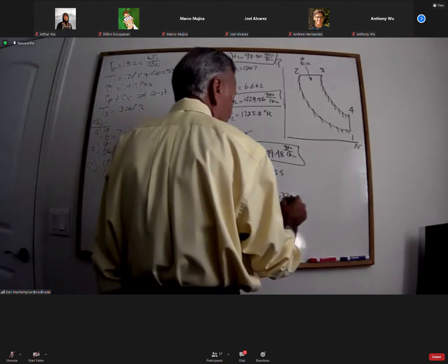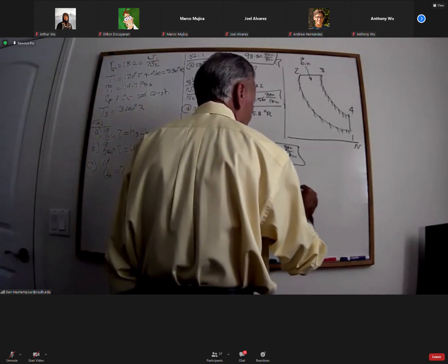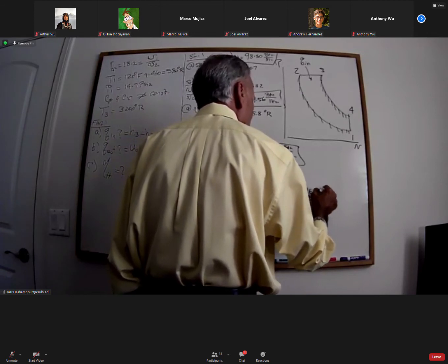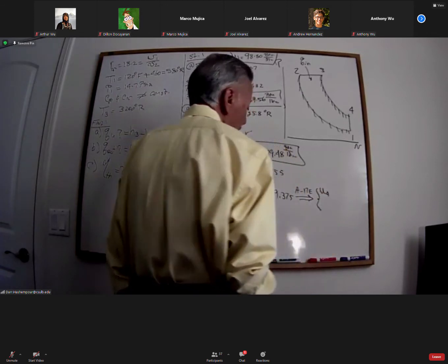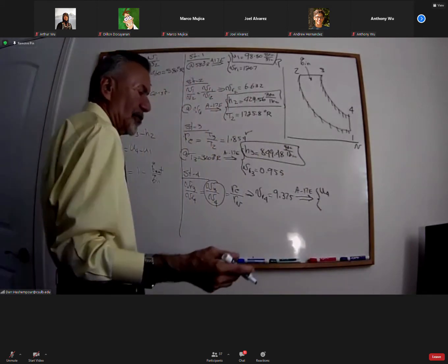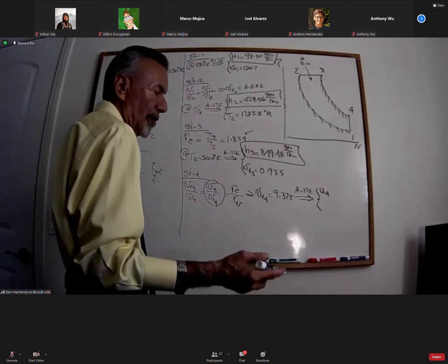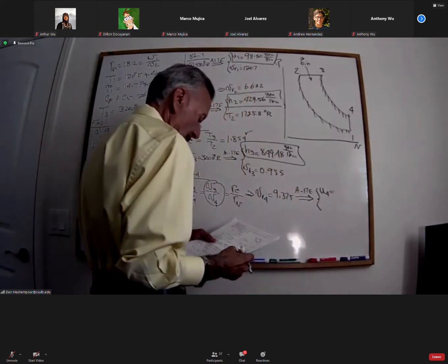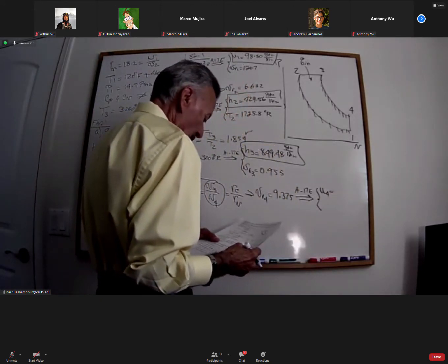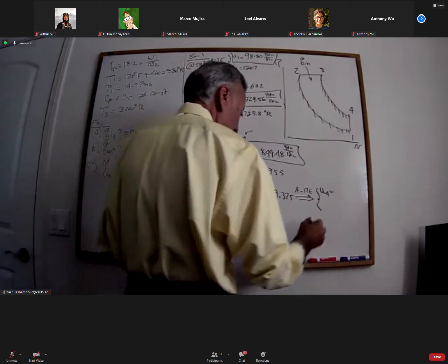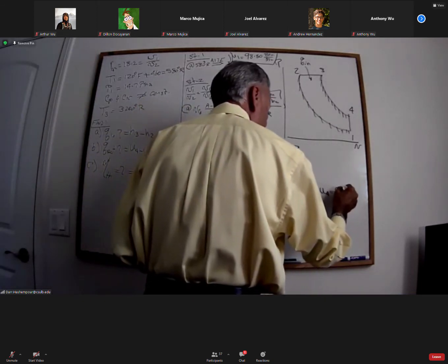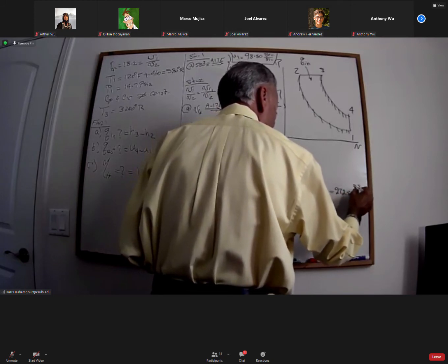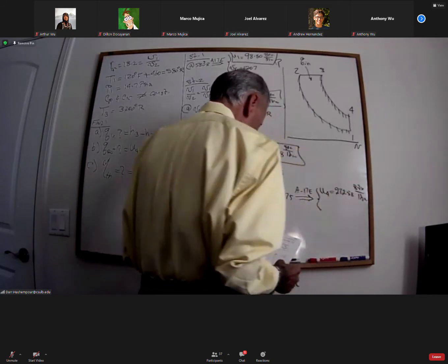Now, once I found it, I go back to table A17E. This time, I find U4. Since they didn't ask me to find T4, I'm not going to bother with it. I just want to find the things I need. In this case, the value of U4 would be 272.58 BTU per pound mass.